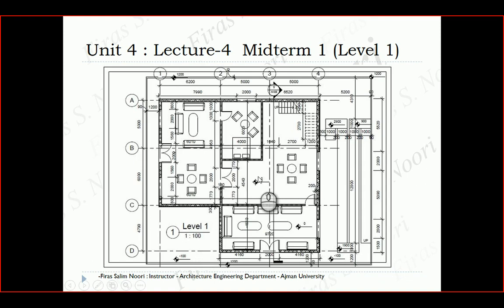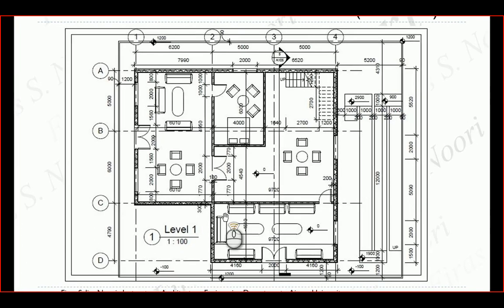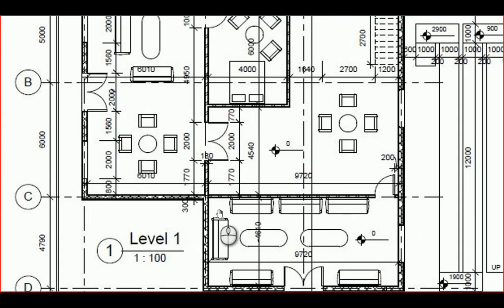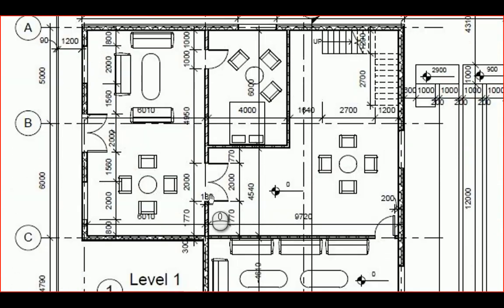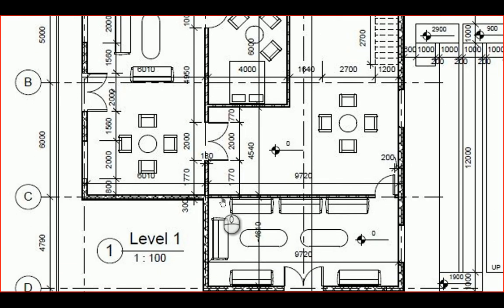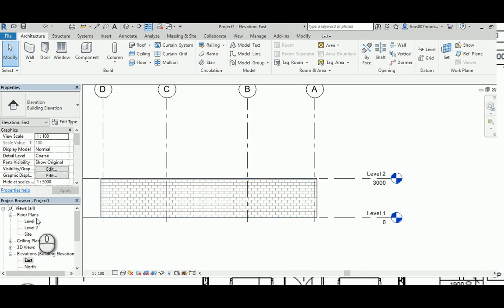Now we might need to do the partitioning actually, so it's a little bit of a tricky thing here. So if you zoom in here, you might see that this partition is aligned to the interior face of that wall. That's another issue to be really careful with. And the same thing is this guy is aligned with the finished face of here. First, let's create the wall, and then we get busy with where to align it.